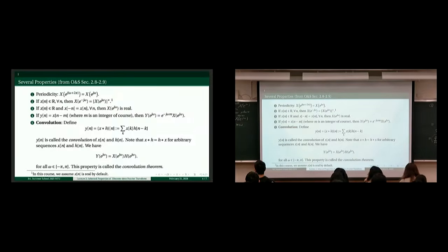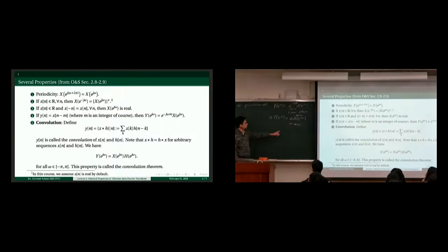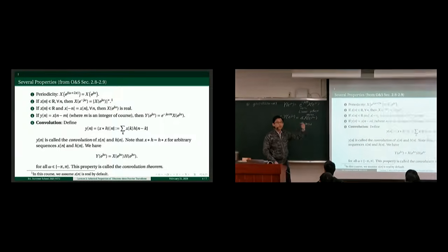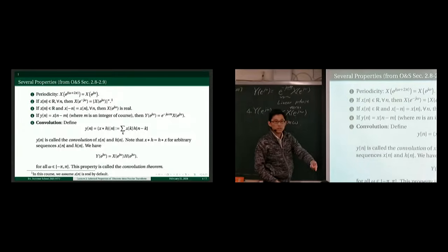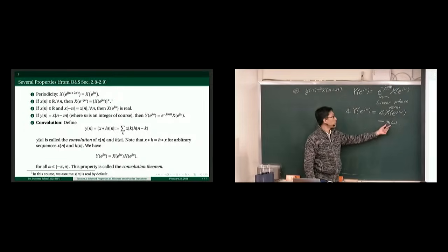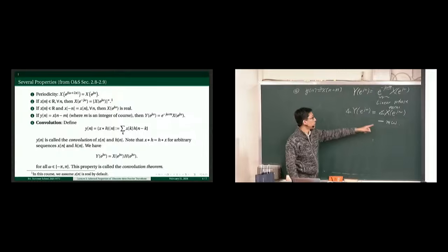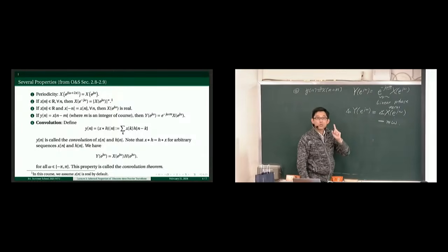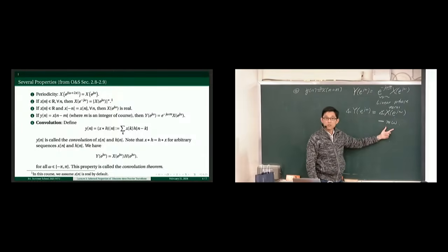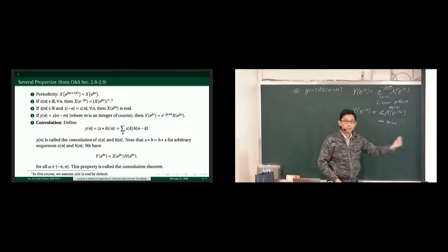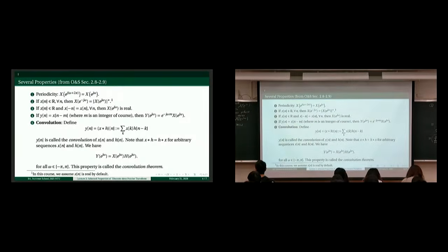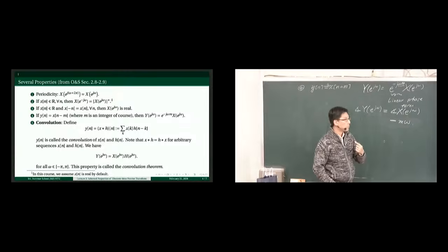So what does that mean? Frequency tells us how fast the phase repeats itself. Therefore, when we move the signal in time by m samples, it introduces so much phase shift. At every frequency, if we just move the time by m samples, then every frequency has a phase delay, by m times that frequency. So that's why we call this a linear phase term.